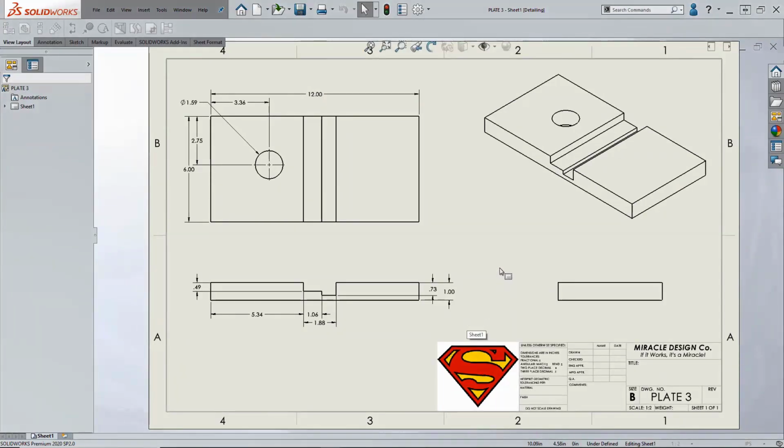Now, the problem that this addresses has been around for a long time. When people go to open up a simple drawing like this, it's not a big deal, and it opens rather quickly. But if you're opening the drawing of a very, very large top-level assembly, it takes a long time. And that's been the issue. What takes so long to open up the drawing when it's just a single page, perhaps, or maybe 2 or 4 pages? What's taking so long? Well, what's taking so long is the fact that SolidWorks is opening up the model in the background.